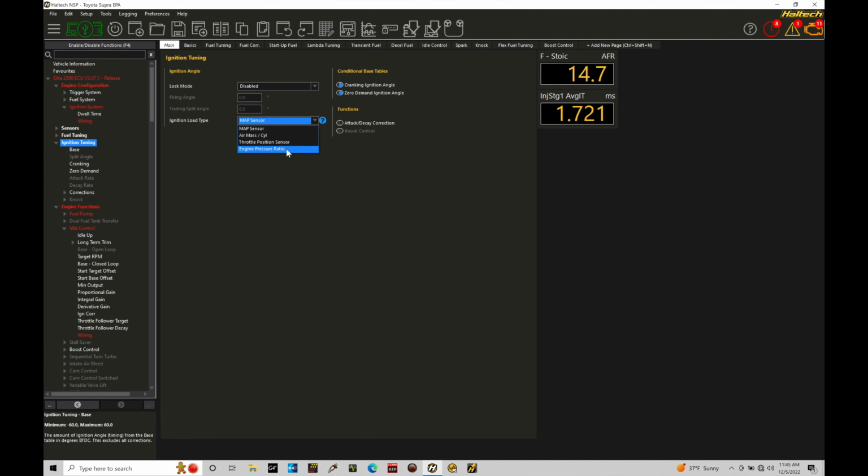That's essentially the efficiency ratio, or engine efficiency ratio. It's a percentage, and it will be relative to MAP pressure or whatever the other scaling factor is going to be, baro or EMAP, and we've talked about that.